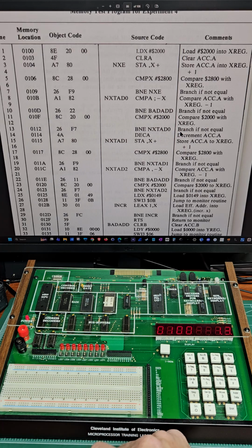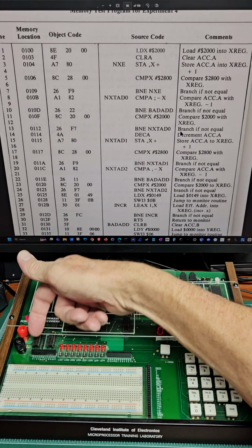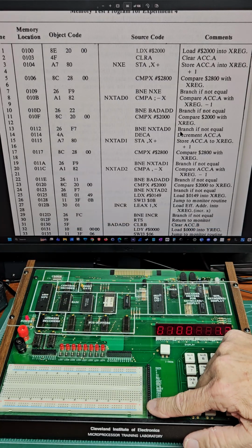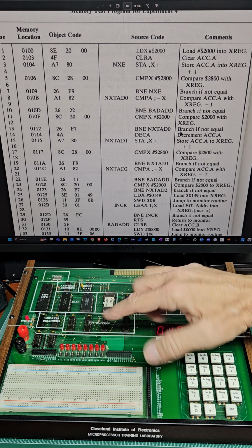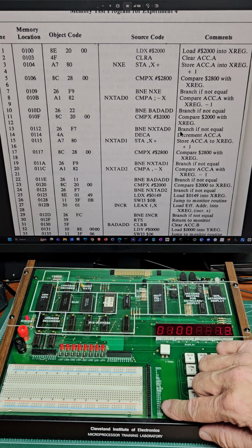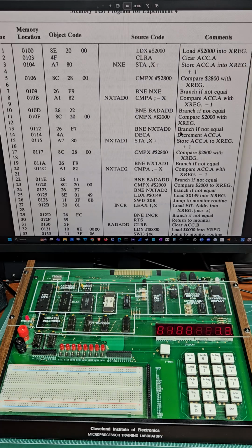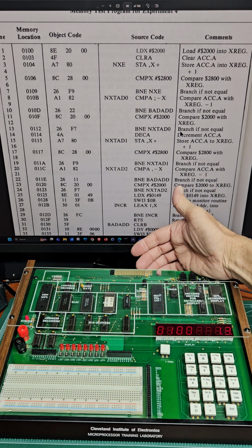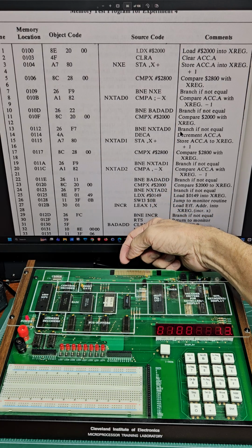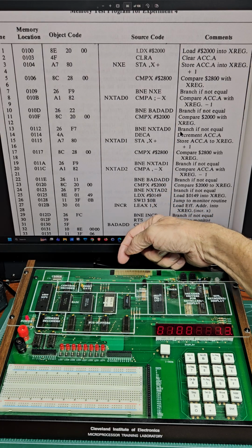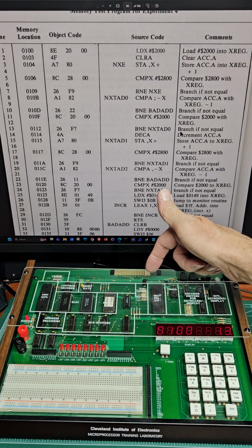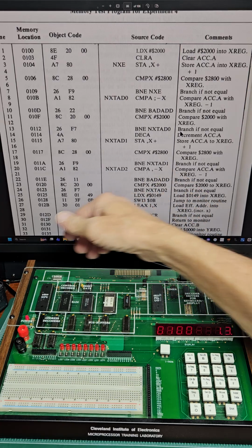So I looked around. At first, I was going to interface it by having a board just sit down with pins that stab down these here. These actually line up perfectly. So if you put a proto board across that and put pins on it, they will stab right down through there with no problem. But then it didn't seem all that great. And I also noticed it has an edge board connector back here. I just had to get an ohm meter and meter it out and figure out which one of these pins went to the address and data and the control bus, and found they pretty much all go there. So I said, well, I'll just use that.